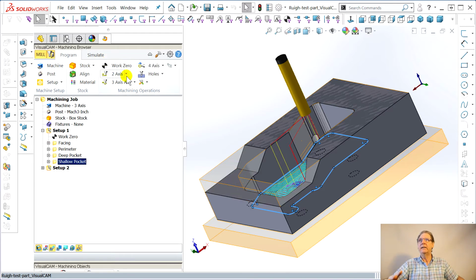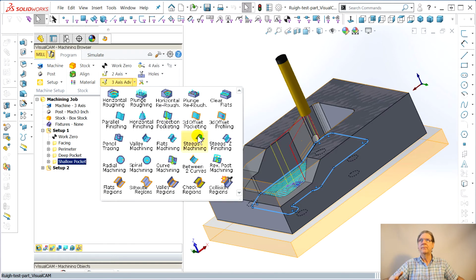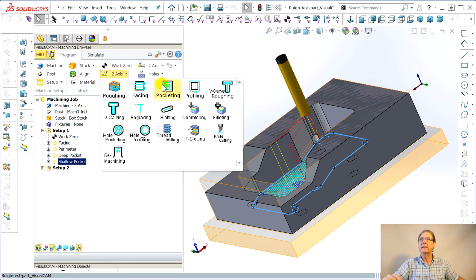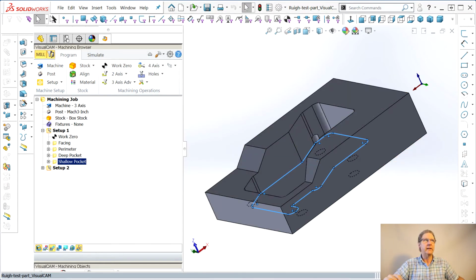Once again, I tried to do 3-axis clear flats. It won't do it in levels. It won't take thin cuts. There's no way to set, oh no, I want to come down on this. I don't want to just whack off, you know, 1/2 inch of material. So I said, now let's fool it. Make it a pocket.